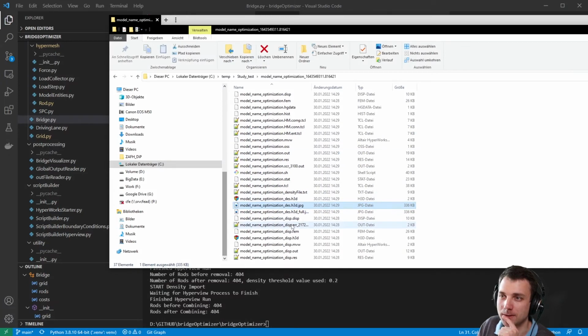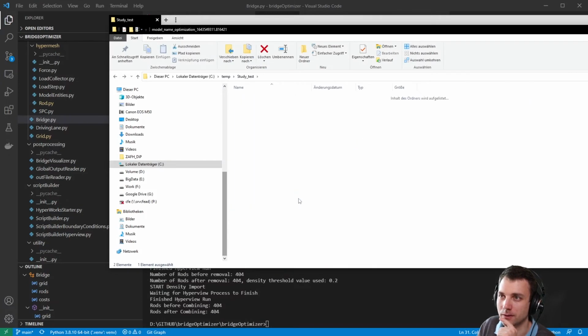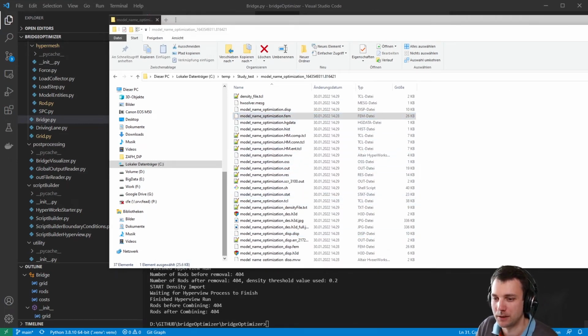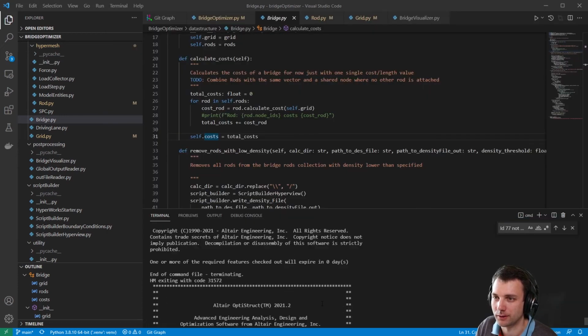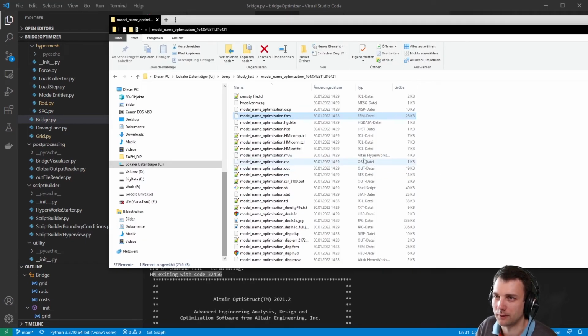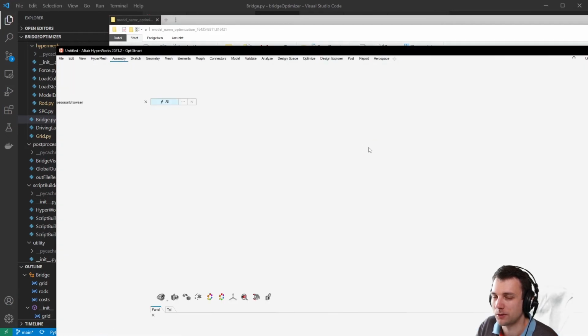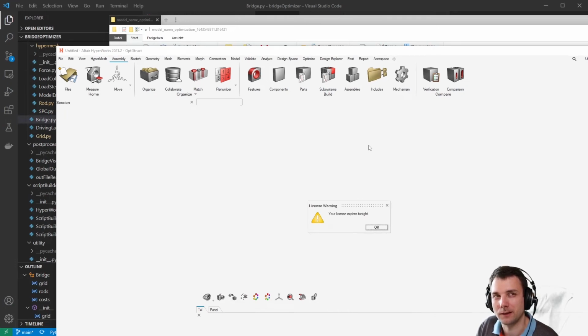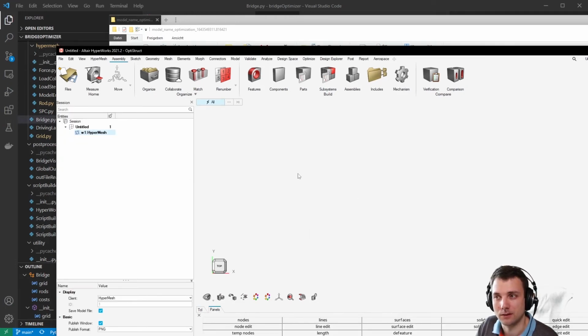And I think now it would be time to look into the finite element model. So we have the FEM file here, and I will just directly import that. See if it, yeah, it tells you the exit code. If that's not 0, something went wrong. And I'm sure it's the compliance thing again, which could mean two things. Or maybe just one thing. I think it's about boundary conditions.